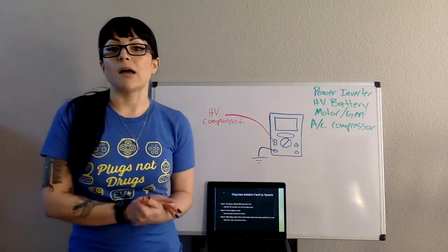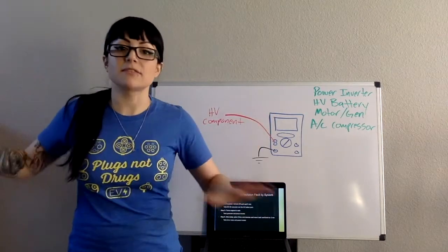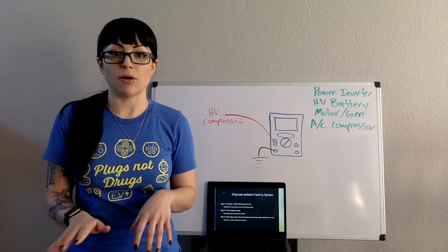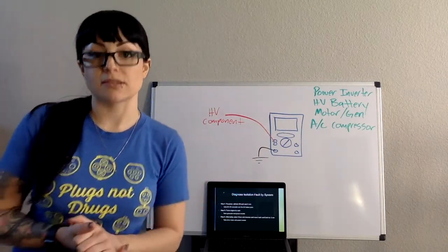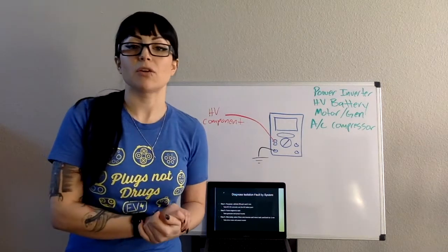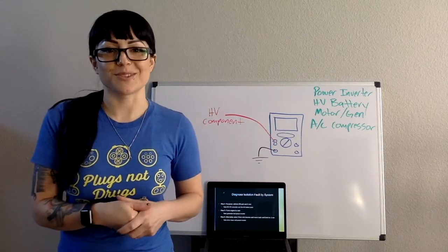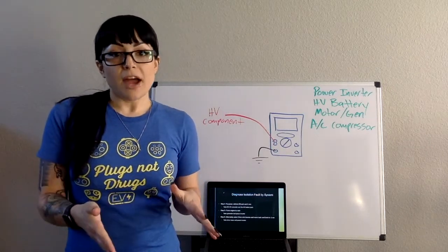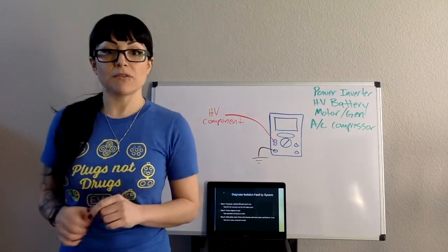And then once everything's off, all accessories are off, everything is off, vehicle is powered down. We didn't remove any interlocks or service disconnects yet. We are just turning it off as if you're driving the vehicle and you got home and you turn it off. Plus all those other things we just talked about. Once you've done all that, where are we at? Step 4 says to repower the vehicle on.